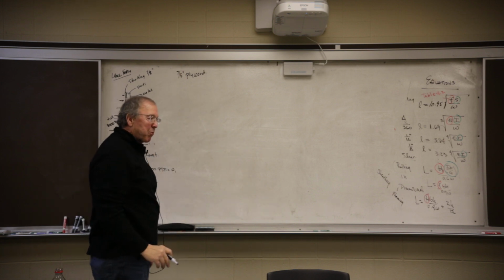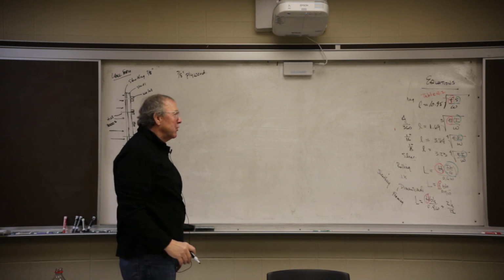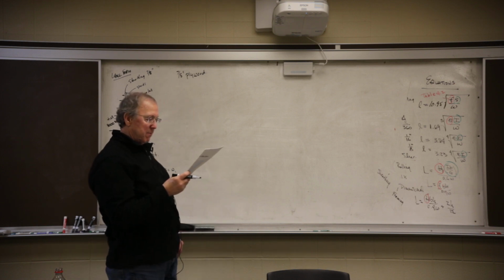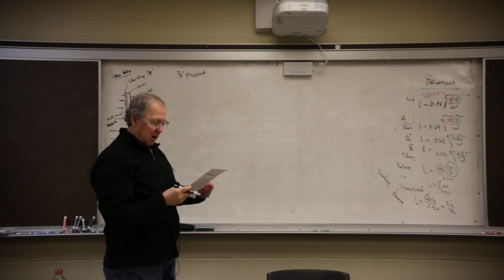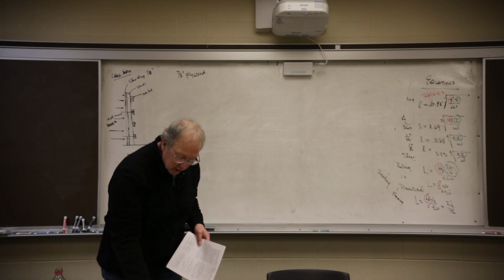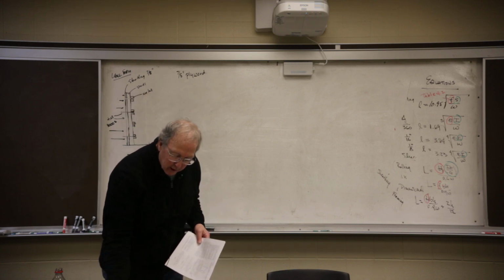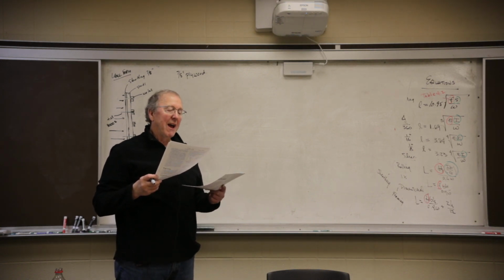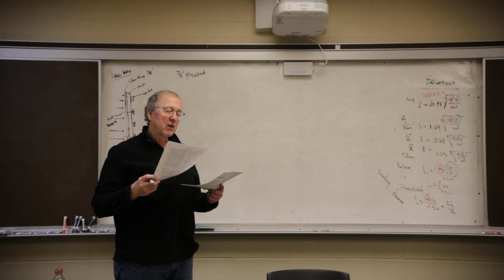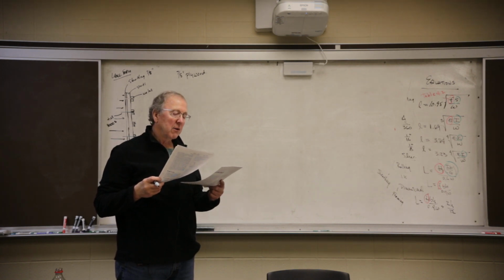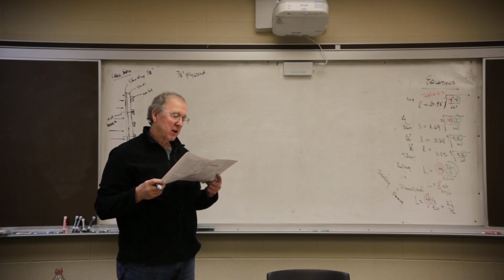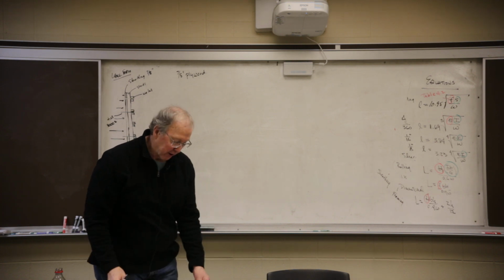I need my properties. What am I going to use for formulas? Well, we just figured P max is 600. I'm going to get to where I know exactly what they've asked. They've asked me for the plywood sheathing, L over 360, and 1/16 of an inch, and then since it's plywood, it's rolling shear.